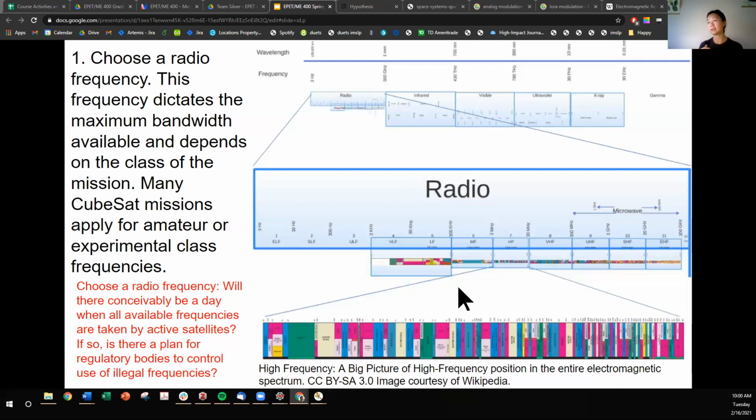There's a term for it called jamming, where you flood that frequency band with some erroneous signal, some noise, and that prevents everyone else in that frequency band from getting a clean signal, something that's actually desired. That's why we control it, and that's why there are different applications associated with frequency bands. And that's why you control the number of people per frequency band.